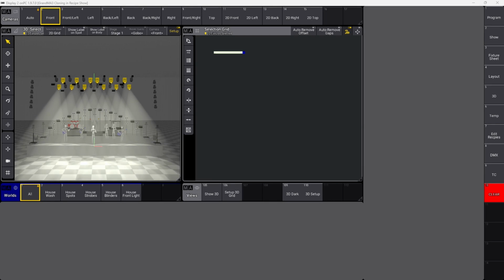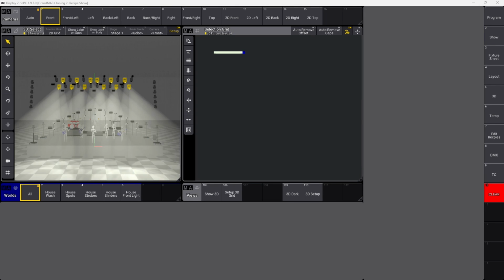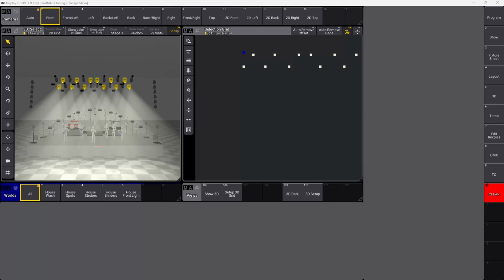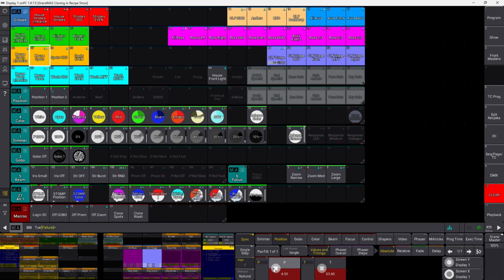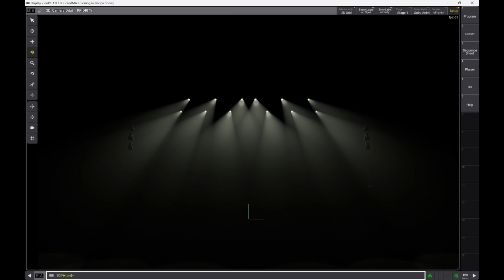I'm going to show you something cool, because if we use the selection grid, we can use something cool. Right now it's not selected, so if I do my fanning here, you can see it looks really odd because it doesn't know where every fixture is. So if we center that and we use our selection grid instead, we put it up into the audience like this. We use the align tool, and you can see it now aligns even though we are on 2 separate trusses, and that is because the selection grid is helping us. It knows where every fixture is, so align actually works even though you might be on 3, 4, 5 different trusses. Align will still make a fan for you very, very easy.